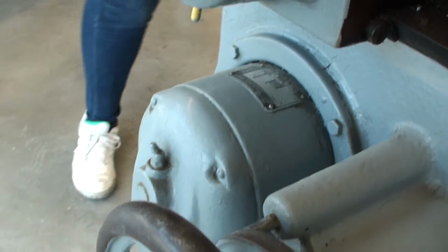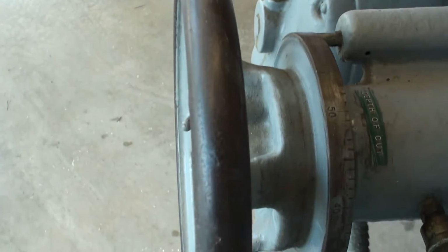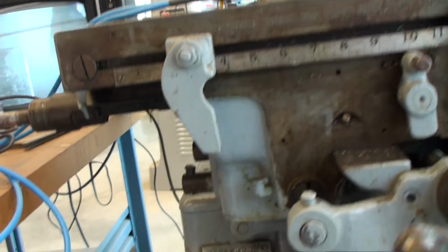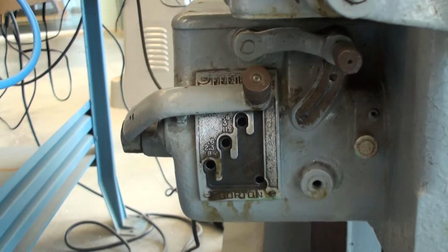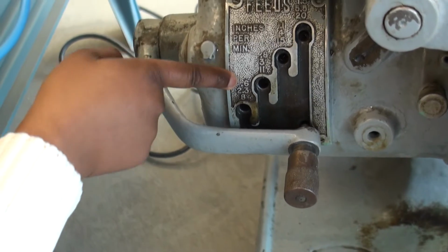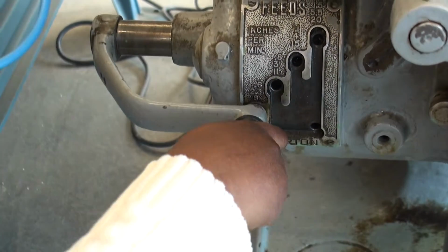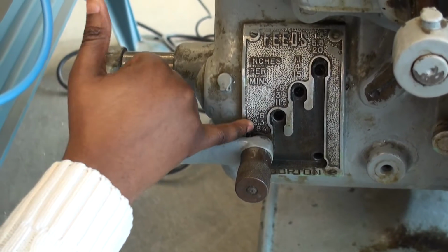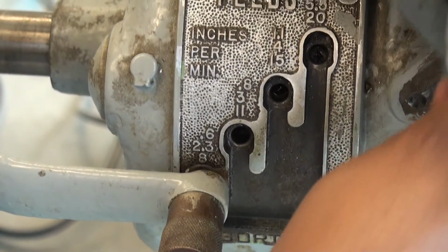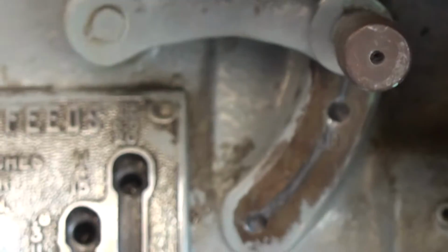All right. So feed rate. Feed rate is set over here. The first feed rate we have is 0.6. So how do we set 0.6? First we bring it down. 0.6 is up here, so we want to bring it all the way over here. As you see, there's 3 numbers here, and this second handle has 3 clicks. Since 0.6 is the first one up here, you want to move it to this indent, but also the furthest one up. So that is our first feed rate.